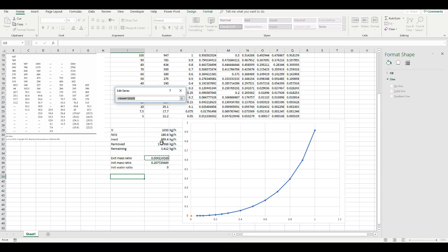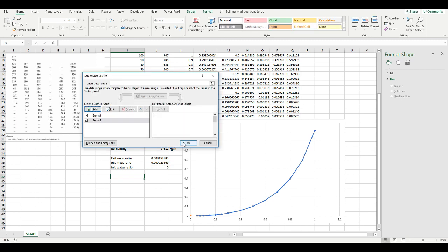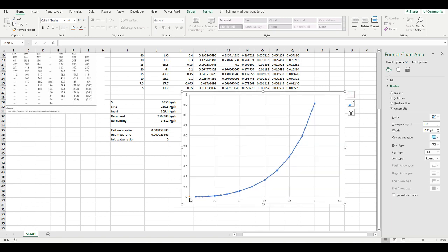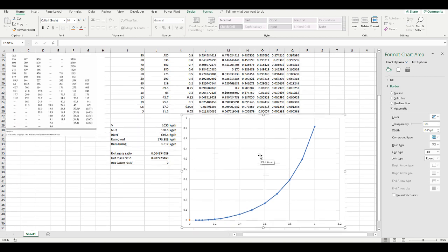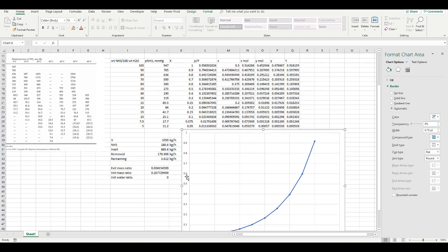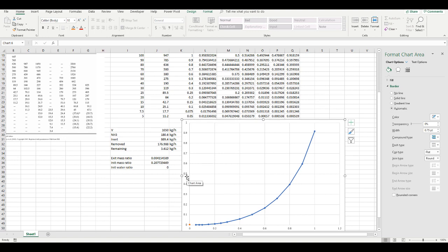And I also seem to have mixed these up, so this would in fact be the correct positions for these values. So as you can see, it's a bit hard to tell, but it is clearly slightly above our equilibrium line, so that means that we are indeed in the stripping problem. Now, we have to figure out where this operating line intersects with the equilibrium line.